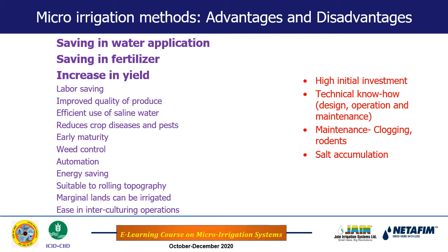Even if we consider a saving of 50% of water by the micro irrigation method, then if I have water which can irrigate 1 hectare of land, and instead of the surface irrigation method we shift to the micro irrigation method, then it is possible for me to irrigate 2 hectares of land, of course if I have the spare land available with me. And you already know the benefits of irrigated agriculture vis-a-vis rain-fed agriculture. I repeat this again because this is important.